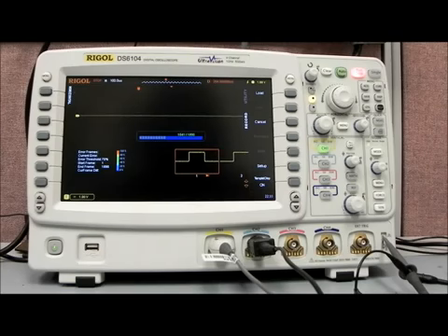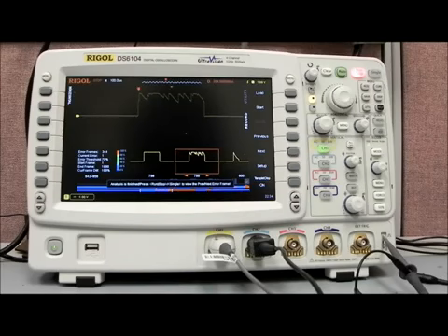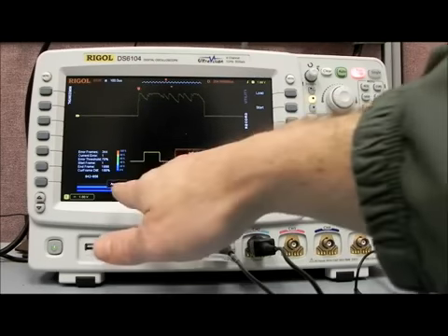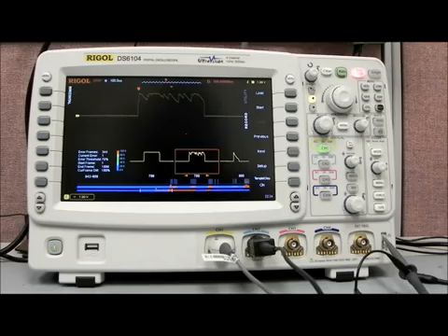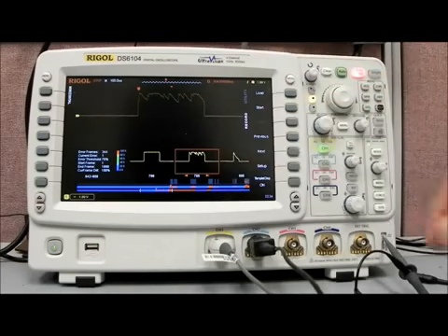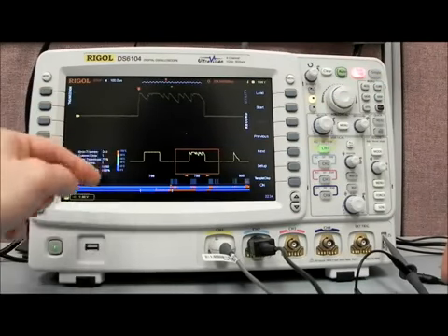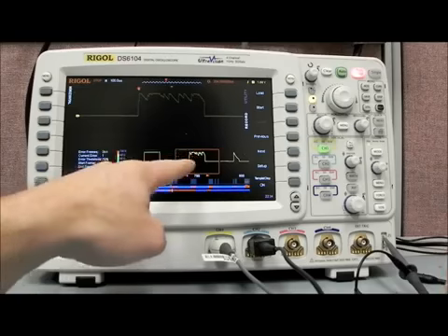I'll just let it run for a second. We're at 1145, 1890, and now it's playing through all of those waveforms. It says analysis is finished, press Run Stop Single to view. Now you can see we're at frame 799. I'll explain a little bit further. This is actually the first error frame.